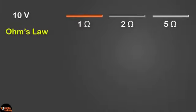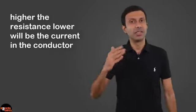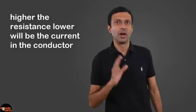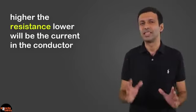Now let's calculate the current in each wire using Ohm's law. Ohm's law formula is V equal to I into R. If we bring current on the left hand side of the equation, we get I equal to V divided by R. Let's substitute the values, and the current in the three wires is going to be 10 ampere, 5 ampere and 2 ampere. Which wire has the lowest current? That's right, the one with the maximum resistance, 5 ohms. Higher the resistance, lower will be the current in the conductor. It resists, opposes the flow of current in the conductor. And that's why the constant is called resistance.